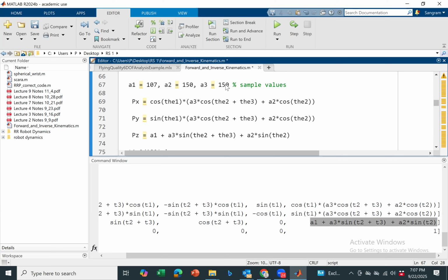As long as the DoBot x0 is aligned with x0 in our kinematic diagram, so your x0, y0, and z0, the zero coordinate frame, should be aligned with the DoBot zero coordinate frame.